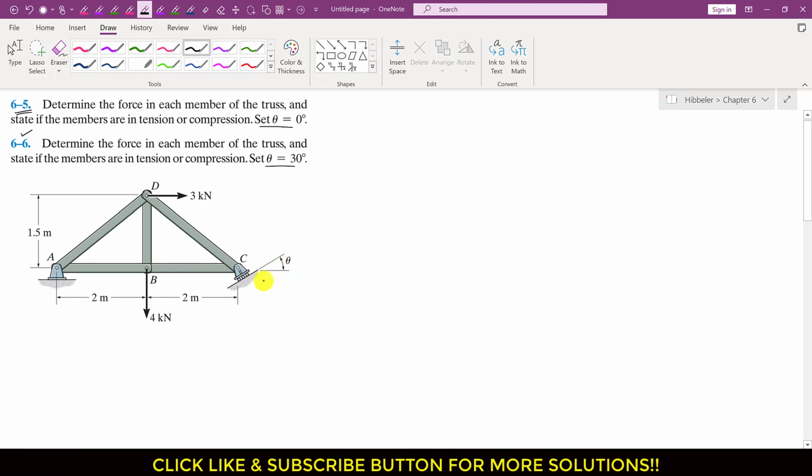Here it is said that this roller is making some angle. The surface on which this roller exists is making some angle with the horizontal, right? So we are given that the surface of this roller is making some angle theta with the horizontal. The reaction at this roller will be perpendicular to this surface, so that reaction will be acting like this, and it needs to be perpendicular to this surface.